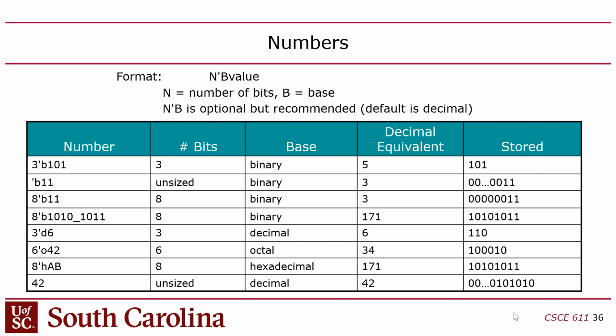So it's good practice to always specify the bit width and the base, for example for a multiplexer, where you're going to say if the select is 0, if the select is 1, if the select is 2. A lot of students in this class forget to do that, and then there's a warning message that sometimes you don't see because it scrolls by with a lot of messages that are printed when you synthesize and simulate. But it's good practice to use this format.